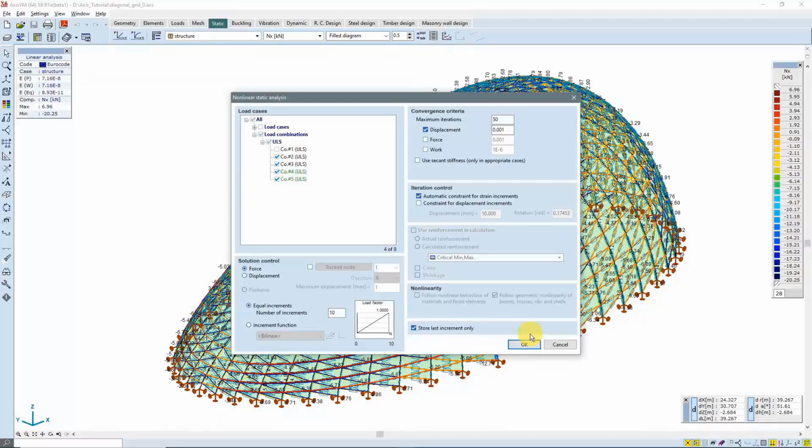For example, I had the 6th mode as a global mode for the grid, but I had the first mode for a local buckling of the column. But if I strengthen the cross section of the column, it can happen that the first mode will be a global buckling mode for the grid, and the 6th mode will be the buckling of the column. So with every change to the model, imperfection shapes need to be revised.